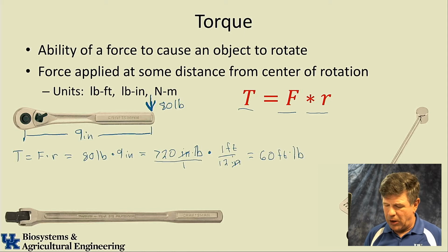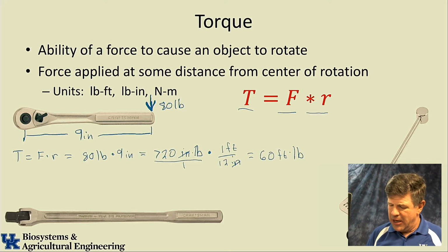So this is what we call a breaker bar, and it's just a longer ratchet. It doesn't ratchet. It doesn't have the mechanism in it that can damage easily, and it's meant just to be a longer wrench to be able to break things loose. And so that's what I would want to use.